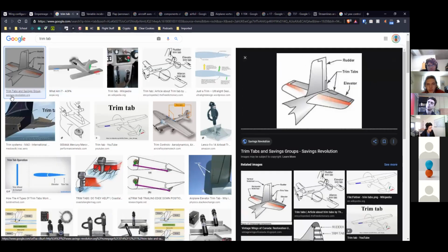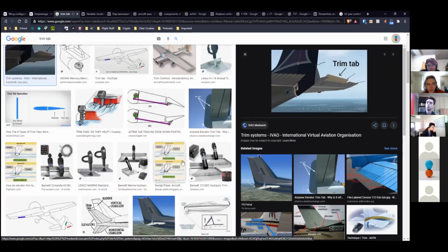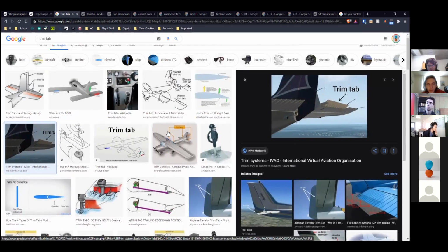But our aircraft, the electronics that control the positions of all the control surfaces, it's commanded like this: the transmitter that the pilot's holding sends signals to the receiver on the plane, and the receiver sends the signals to all the servos that control the position, and there are controls on the transmitter to mix trim into the control signal.